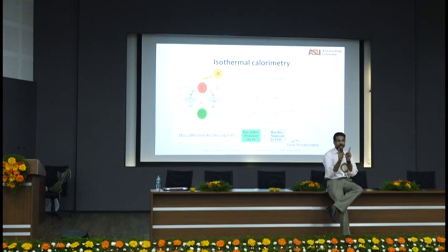Two different competing things. The heat is trying to increase the rate of reaction, but the system is trying to come back to an equilibrium. Which process wins in which part of your concrete determines how the microstructure of that part is going to be. Therefore, if I have a mass concrete, and you bring the same concrete from the same truck, the microstructure on the outside and inside of the mass concrete are never going to be the same, because this competition is never one-sided. It keeps going back and forth.